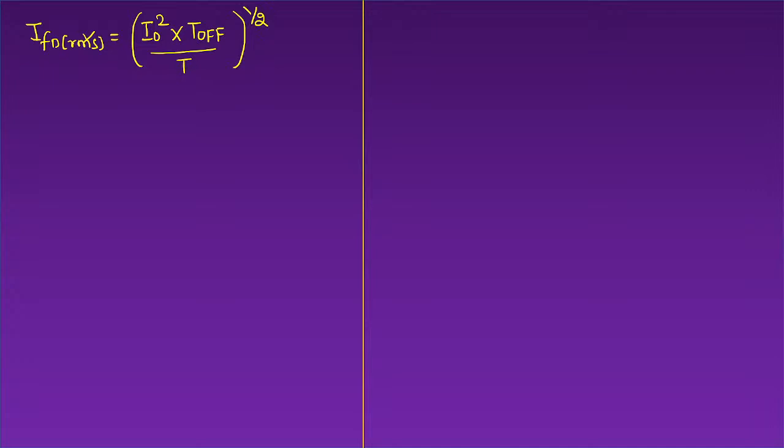I'm repeating one more time. Mean means average. Average means area by time period. Area is width into height. I have written that. Then mean square. Square means the magnitude of the height is squared. Next, after that I should take the root. That is what I did.